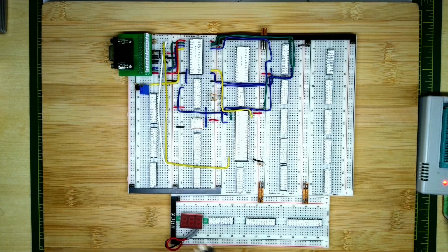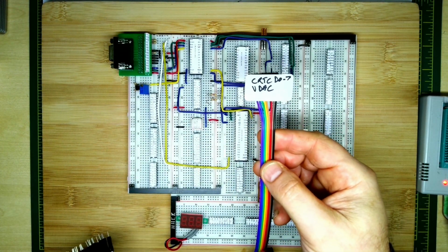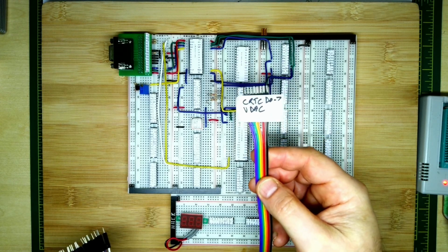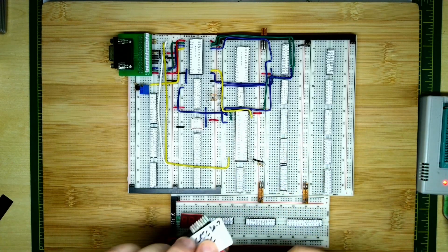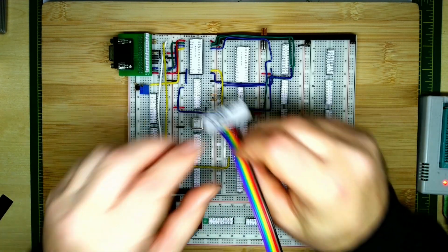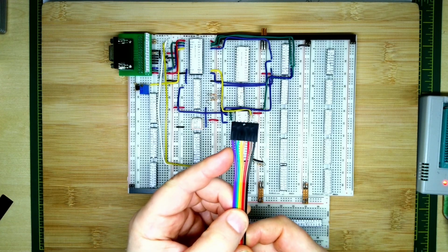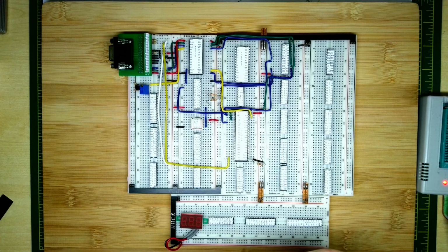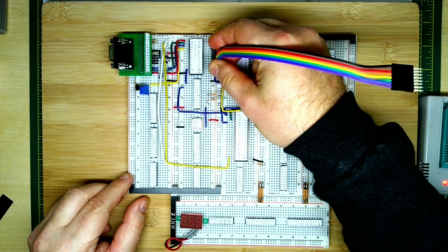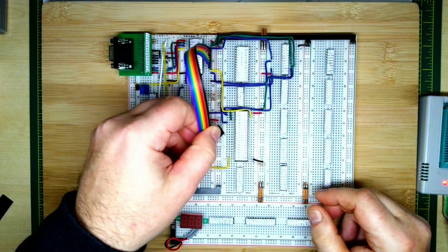And what I've done is made up a load of cables. So what I tend to do is take this cable, and this one here, for example, I've labelled up as the CRTC D0 to 7 to the video DAC. So this is going to go, in fact, from here to here. So I'll take the label off now. Generally I tend to use purple as pin 1, which is consistent with the logic analyzers that I use. So generally purple goes to D0, and then you plug this in down here as well.